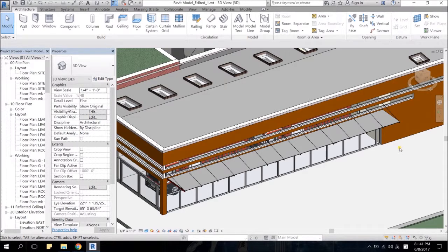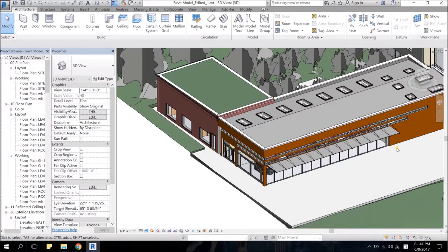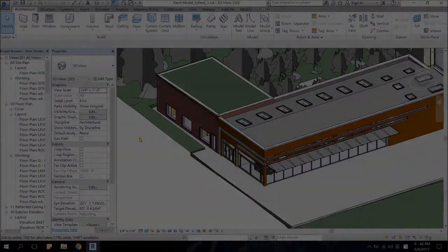And we'll see the difference between before and after the redesign. After the revision, we can redo the whole process. We can export the Revit file as a DWG file and import that file into Rhino and rerun DIVA for the daylighting simulation.